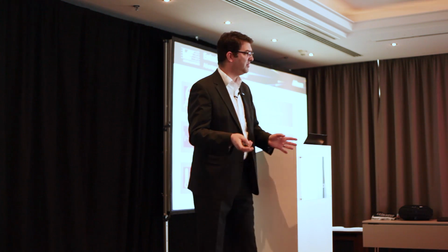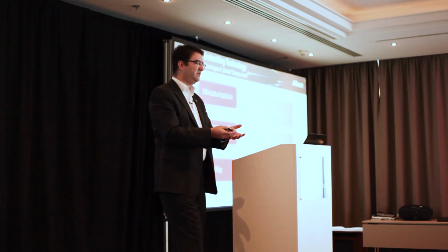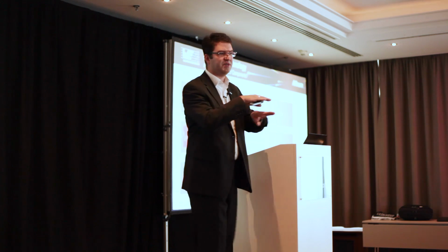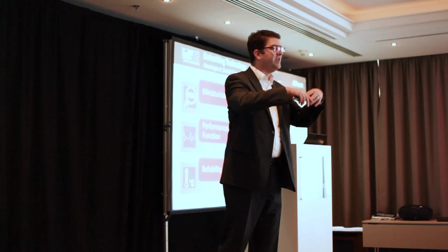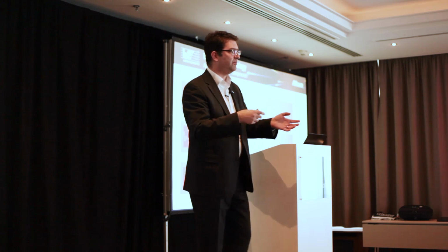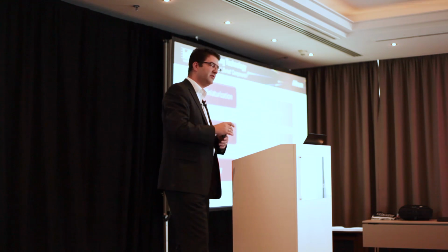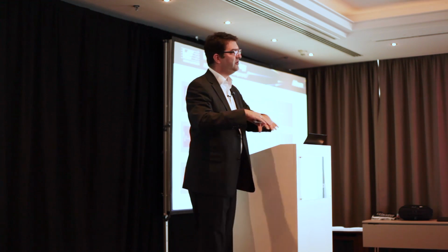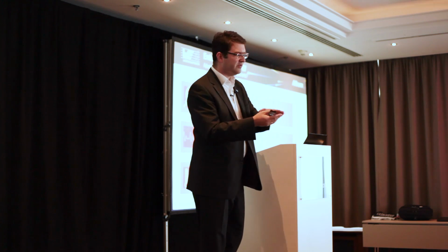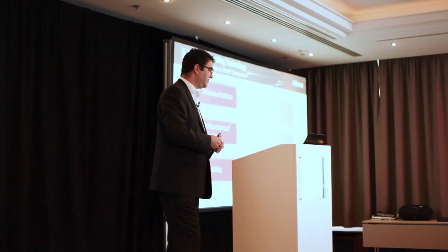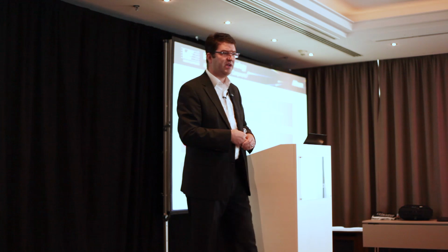So by embedding the components, we could get rid of this transfer mold. Everything is inside the PCB material, so you do not have two different materials working against each other when you look from the outside. You for sure have your components and the PCB material, but that's a different topic. From the outer layers, you have one material, so this crack won't occur that fast. So we could increase reliability by times 3 or 4 with that setup.